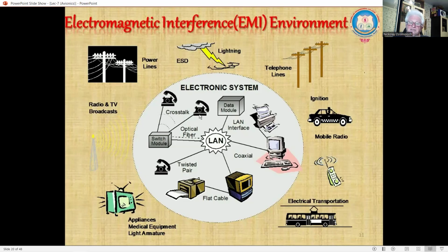The incoming wires from the cable to these units or boxes must also be terminated with electromagnetic filters, which present a low impedance to EMI-induced transient voltages in the cable. The transient voltages are thus attenuated before they can affect the circuits inside the box.